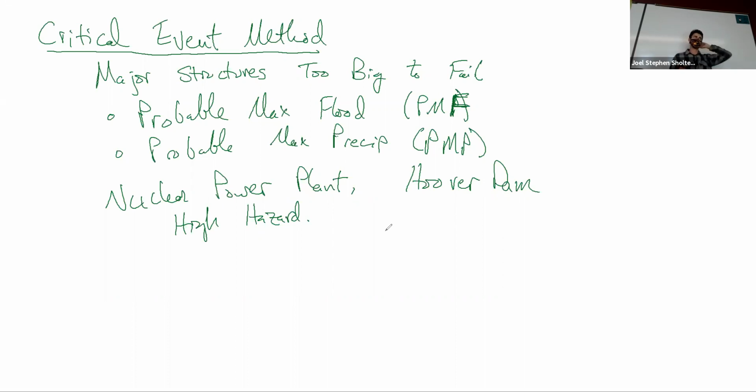I've done a bunch of scour analysis for pipelines, and you know, you've got these crude oil pipelines that are like 3 feet under a major river. There were 2 spills back-to-back years on the Yellowstone River because the pipelines were scoured and broke from flood events. They just weren't designed well. We don't have very strict standards for that, unfortunately. I think because of those catastrophes, things are changing.